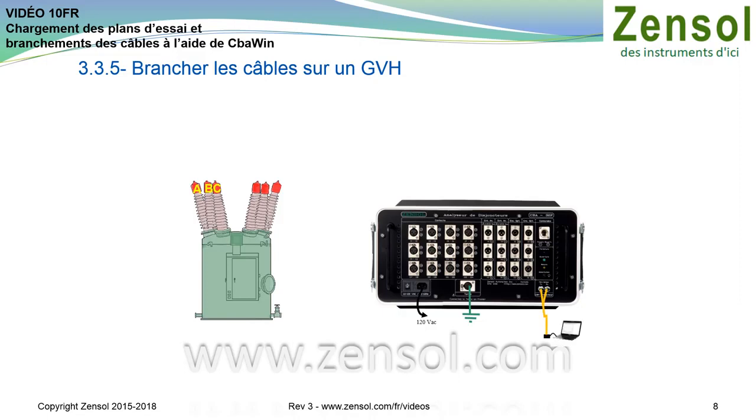Connect the fiber optic communication module to the computer. Pay attention to TXRX indications. T for transmission, R for reception. You'll find the explanation in Zensol's manual, the quick installation guide. The control cable is connected to the coil or relay, depending on the circuit breaker.